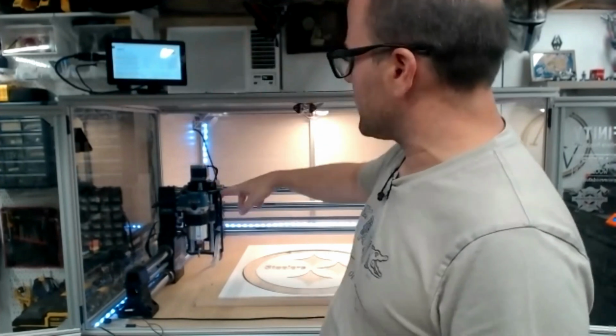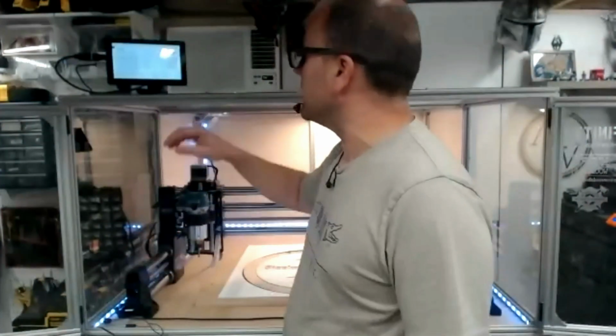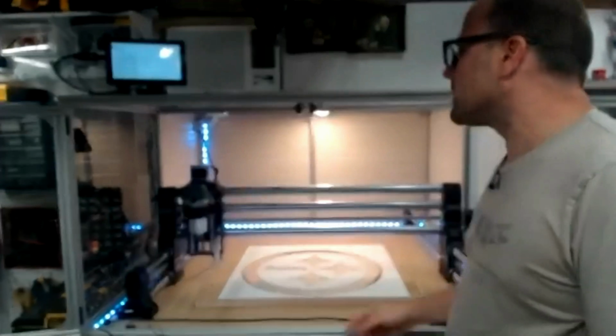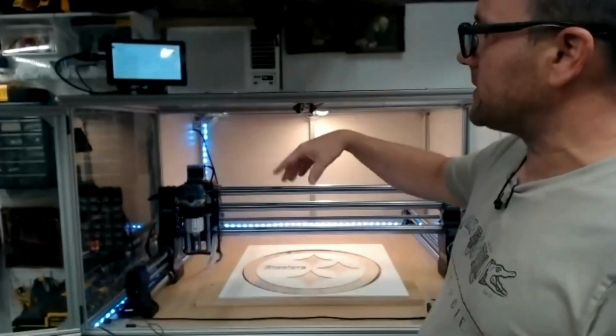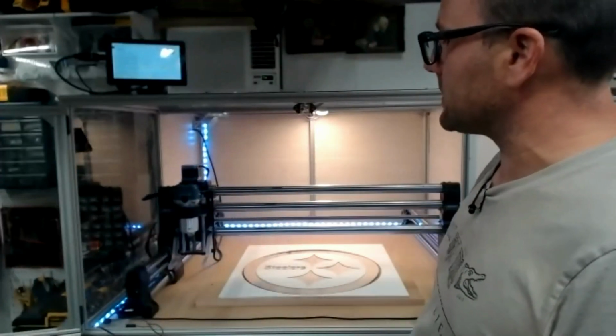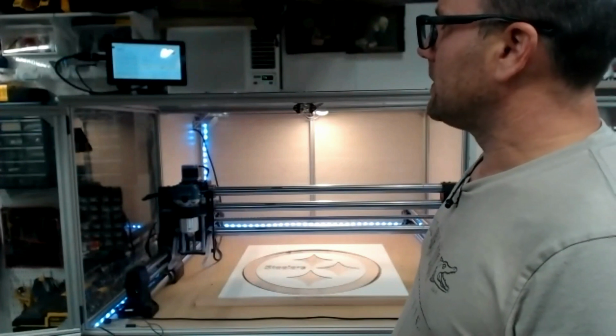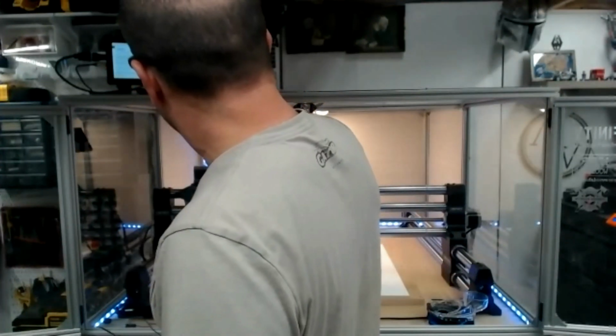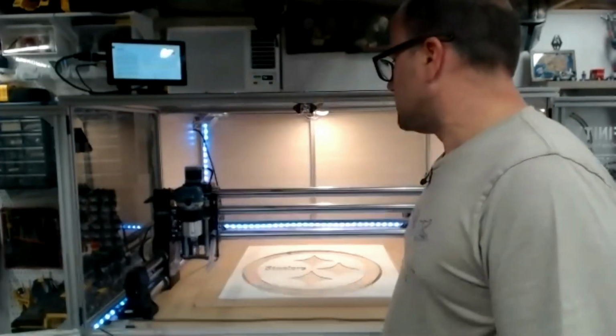So we want to home it first, which will bring it to the front. If I click home, I'm just going to home everything. It homes the Z first, even though I hit the button that says do all. It just doesn't do it in succession. Yeah. Most 3D printers do the same thing. They always home Z first, and then they do X, then they do Y. They never do it all at the same time. Yeah. For some reason it didn't do Y there. Now it's doing Y.